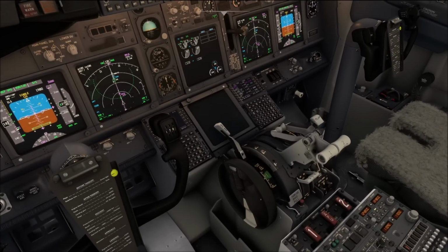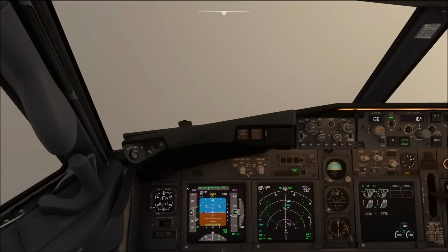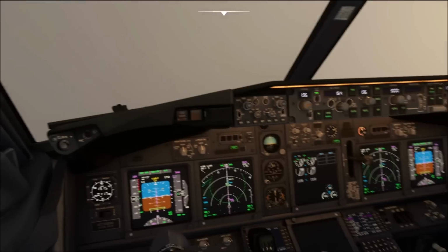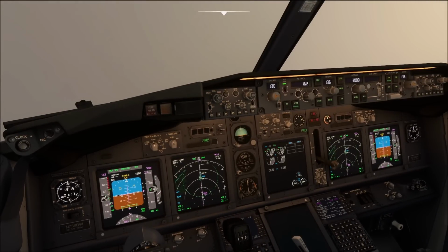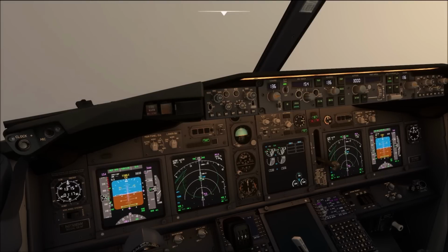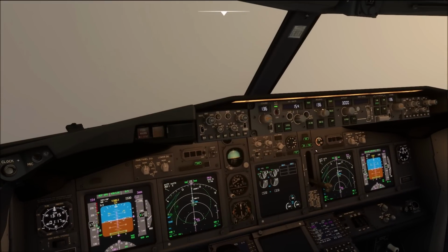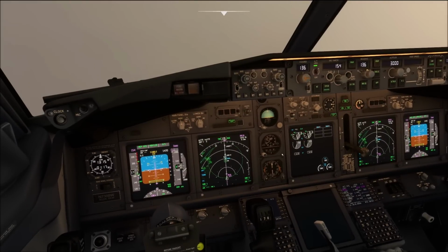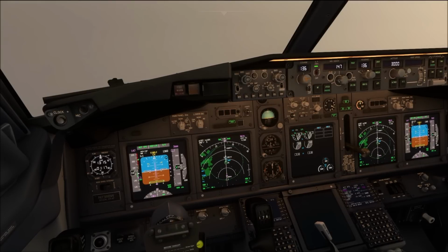Let's help us a bit. Flaps 10. We're approaching a 5-mile range. Gear down. Flap 15. Landing checklist. Once again, entirely standard checklist here. Start switch is continuous, recall, check, speed brake on, green light, landing gear down 3 green, auto brake 3 set. Okay, let's go flap 25 intermediate. And flaps 30, complete the landing checklist.